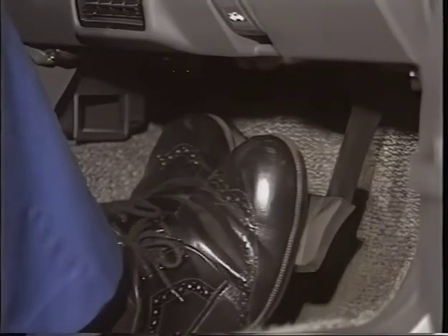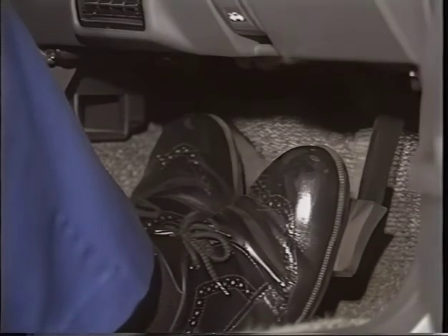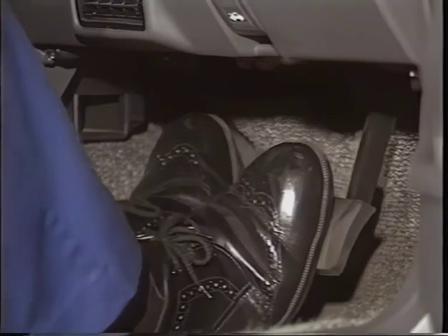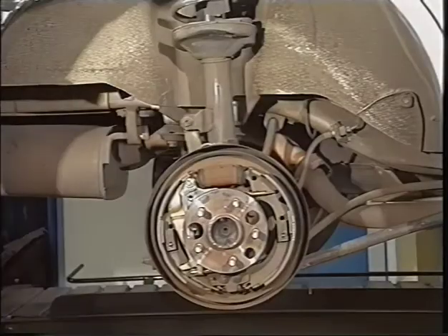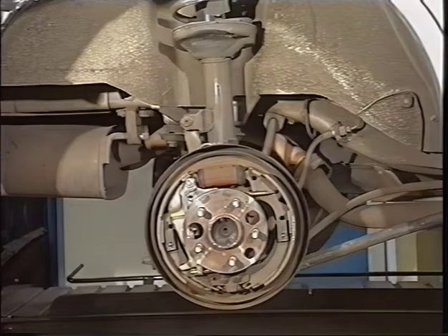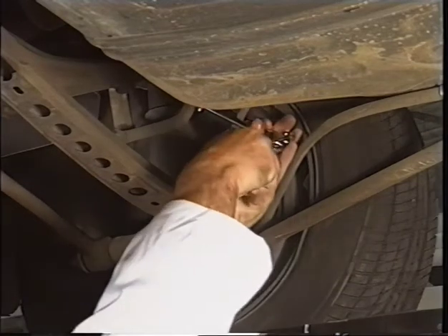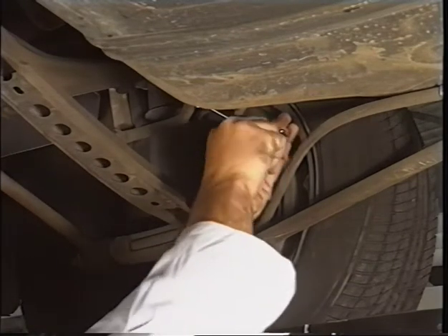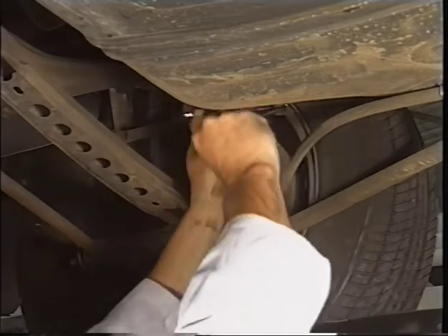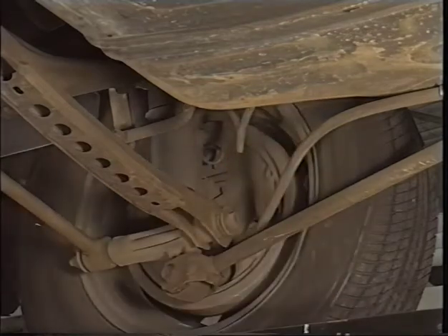In this way, a brake or brakes which have excessive travel will have been easily identified. In a high percentage of cases, it is the rear brakes, particularly those systems which have drum brakes on the rear, which cause problems. Because of this, it is normal practice to release the rear clamp or clamps first. In this way, comparisons between wheels or axles can be easily performed.